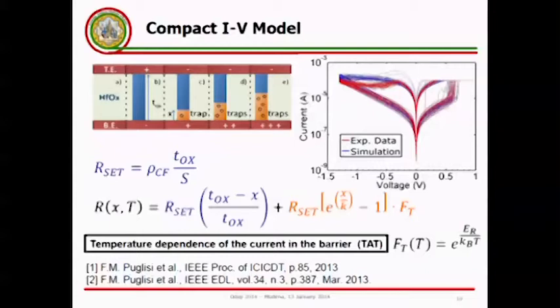In this state, the conduction can be approximated as quasi-ohmic, and its resistance can be expressed in that way with the first equation. That's a really simple but powerful equation, since through simple IV measurement we can estimate S, which is the cross-section of the conductive filament, which is the most important parameter, since the resistivity of the conductive filament is widely known in the literature, and also the thickness is just the physical thickness of the oxide layer.